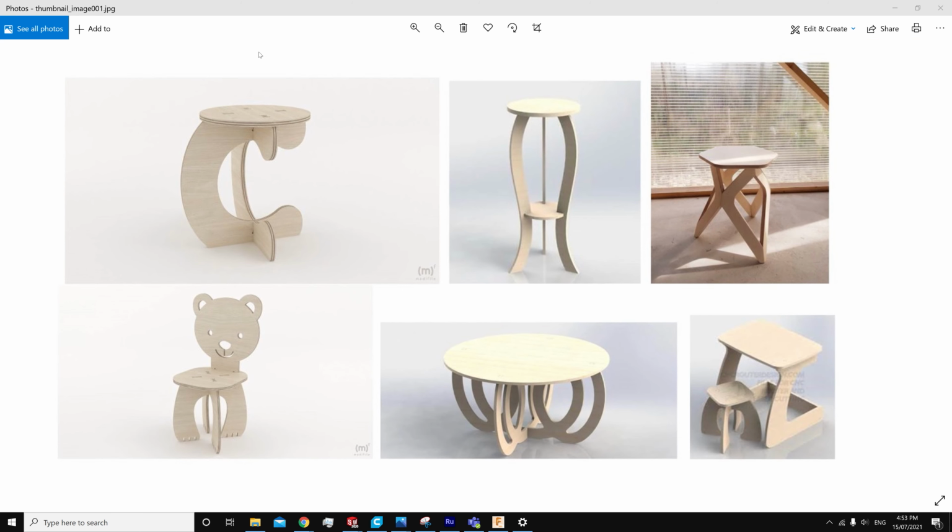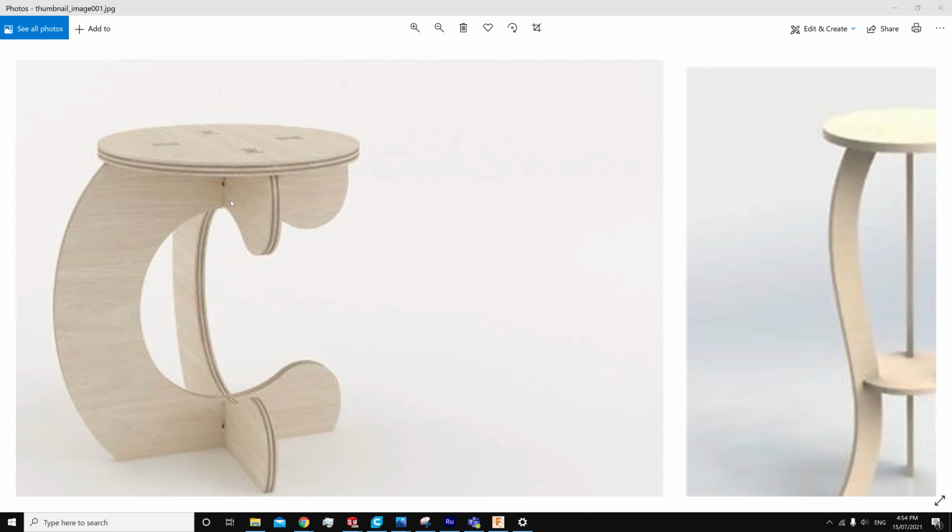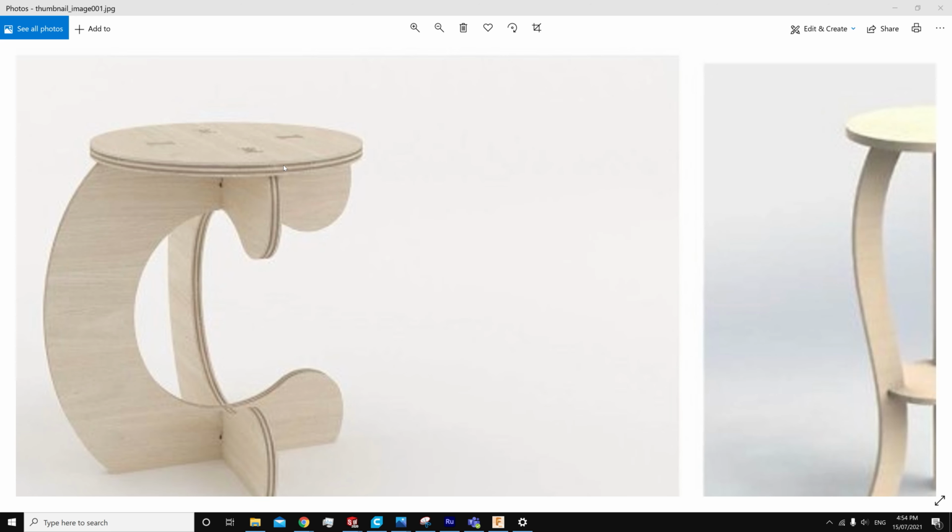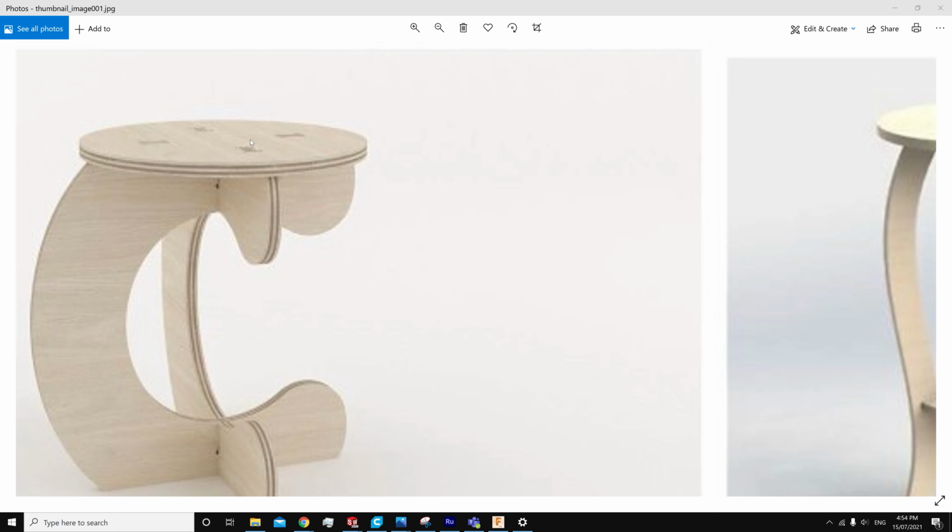So a dog bone is called a dog bone because it looks like a dog bone. Essentially, if you've got a rectangular or square cutout in a piece of material that you want to cut with a CNC router or a CNC machine, that CNC router is going to be using a round cutting tool or a round end mill. Normally, I'll use a 6mm or 4mm diameter tool. That means in the corner of each internal cutout, or internal corner, there is going to be a radius of between 2 and 3 millimeters.